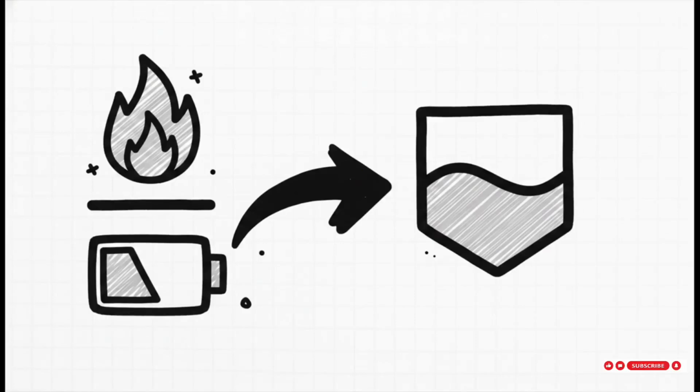Now, what if you're working on a problem and you need to relate that heat equivalent directly to the charge equivalent? Engineers use a really handy ratio for this called the form factor. It's strictly defined as the RMS value divided by the average value. So, if you divide our two constants, 0.707 by 0.637, you get exactly 1.11. For a pure sine wave, the form factor is always going to be 1.11. It's just a really quick, reliable way to check the shape and efficiency of the wave you're dealing with.